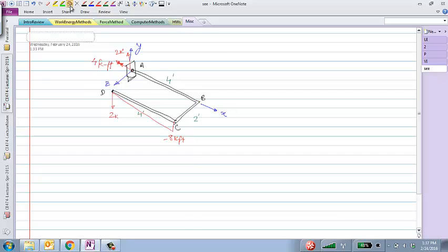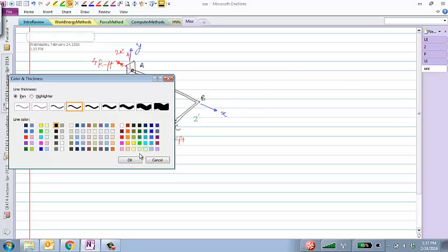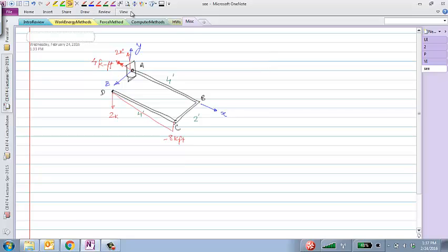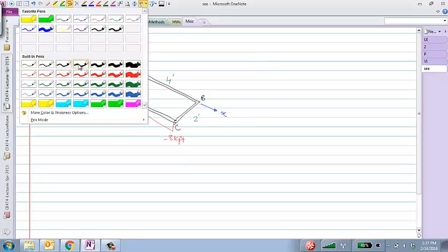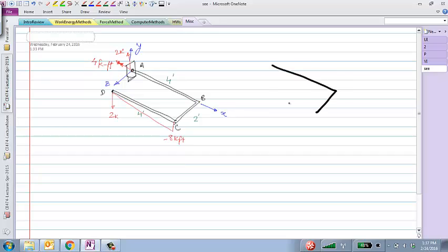Where does that bending moment go? It becomes torsion in this guy, right? So maybe I'll draw that as a separate torsion diagram. So if this is my structure and my torsion diagram, so this is, let's say, M and this is T, then the torsion diagram clearly would not have any torsion in this last leg, and this 8 kip feet would become a torsion in which direction?